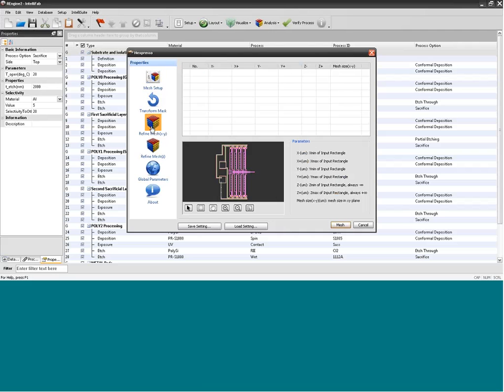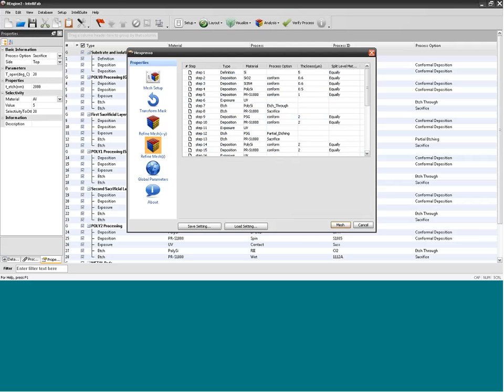As you're creating your mesh, if you have a certain area on your structure that needs a more fine mesh, you can just drag that box and input the mesh size that you'd like to have around that certain part of the structure. So that's very useful for really optimizing your mesh of the structure. You can do that in the X, Y direction, or in the Z direction as well. So if there's one certain layer that you want to have a more fine mesh on, you can split it up more finely.